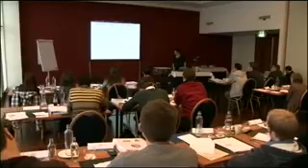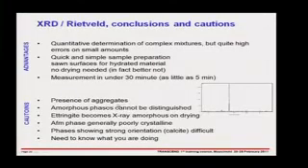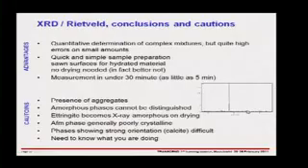The big disadvantage is the presence of aggregates. So this shows a diffraction pattern from concrete, and you see this huge peak here. This is quartz, because a lot of aggregates contain quartz. And you see that because you've got this huge peak for the aggregates, all the peaks for the stuff you're interested in become very small and very difficult to analyze.